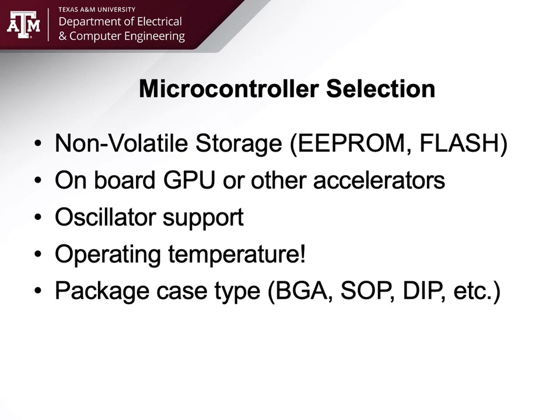Pay attention to that. I'm going to say this is also in the common pitfalls as well, but I'm going to say it here. If you're using a Raspberry Pi, order the heatsink. You will need a heatsink. Do not think you don't need a heatsink. If you don't order the heatsink, we'll be replacing your Raspberry Pi at some point through the project. I can guarantee it. Because what happens is you start actually processing with the Raspberry Pi, and it eventually burns up because it doesn't have a heatsink. It works great and doesn't get hot when it's sitting idle, but as soon as you start doing actual processing with it, it gets hot. It needs a heatsink and possibly even a small fan.